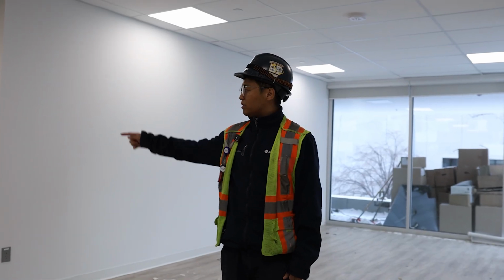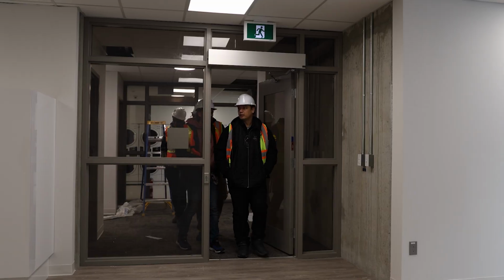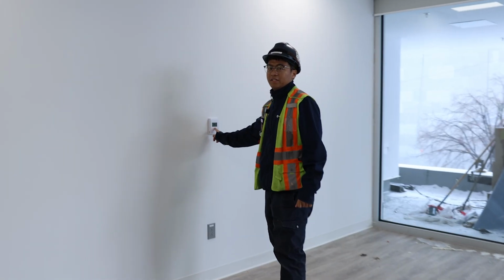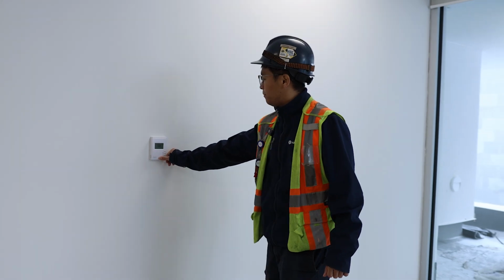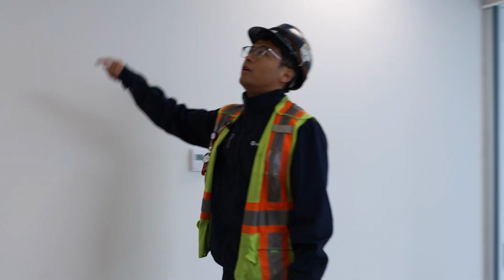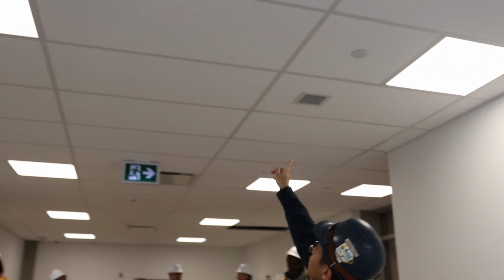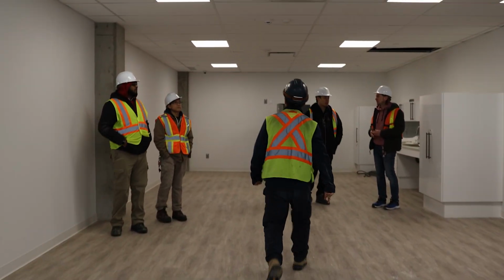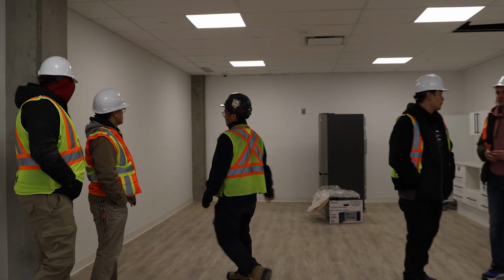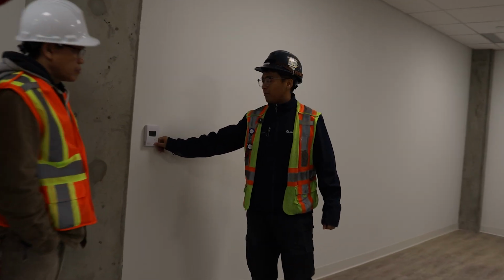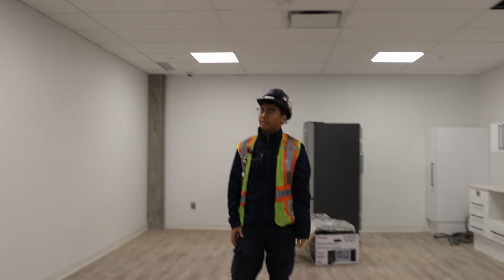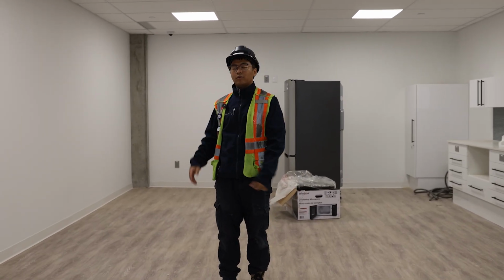If we walk across the hallway in the amenity room, we have fan coil unit number 1 and number 2. This is the thermostat for fan coil number 2. It's labeled fan coil 2. The unit will be in here, above this ceiling tile. And this is the thermostat for fan coil unit number 1. The unit will be right here. If you pop up this ceiling tile, you will see the unit. The DDC control panel is also next to the unit.